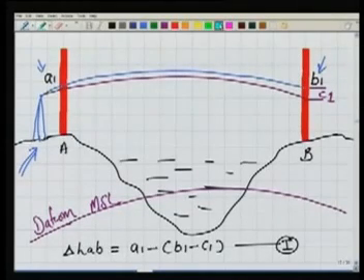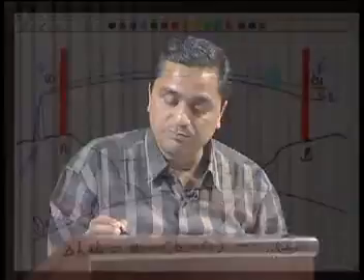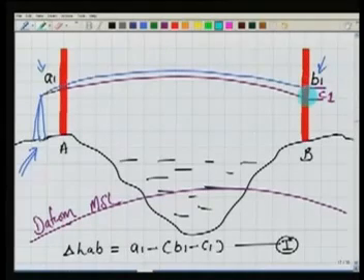Then next, our desire is, as we know, that the surface along which I am taking the observation, this violet one, should be parallel to the mean sea level or our datum. This is what our desire is. But this is not the case. We know it. We try to make the line of sight horizontal. Still it is not horizontal, slightly in some curve. So basically we are observing along this blue line to B1. Ideally I should have seen at C1, because this violet line is parallel to our datum.